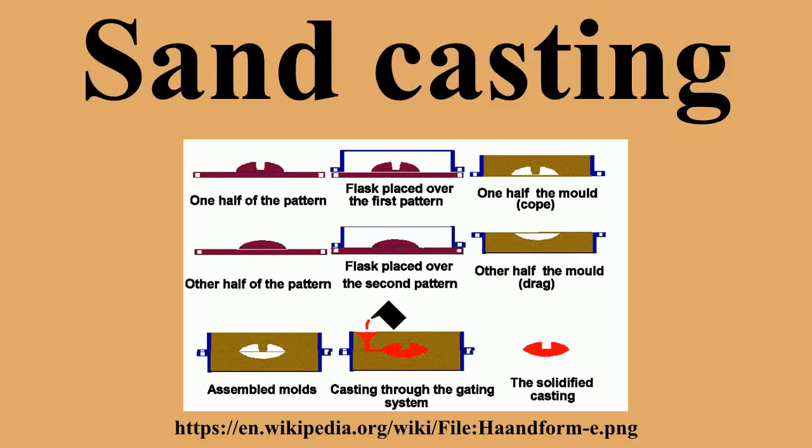Air-set castings can typically be easily identified by the burnt color on the surface. The castings are typically shot blasted to remove the burnt color. Surfaces can also be later ground and polished. For example, when making a large bell, after molding, the casting is covered with the residue of oxides, silicates and other compounds. This residue can be removed by various means, such as grinding or shot blasting.